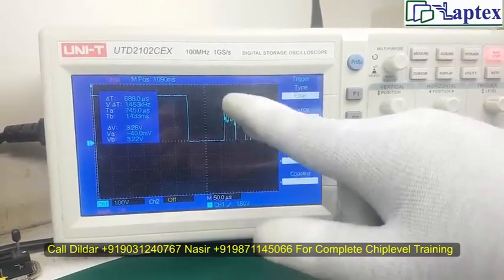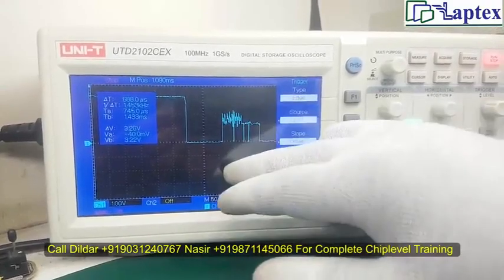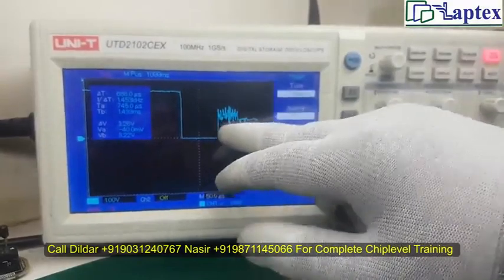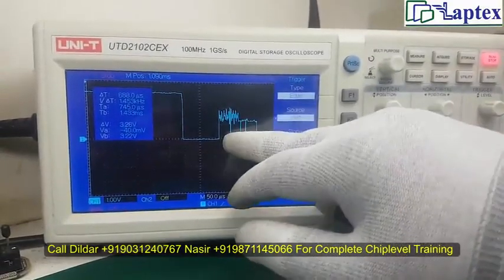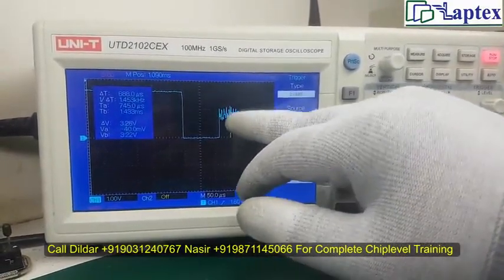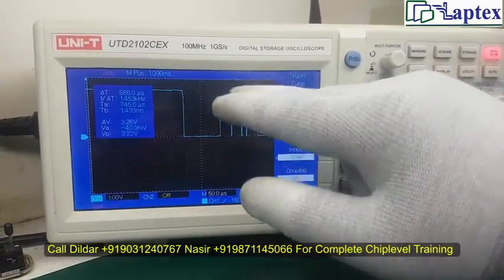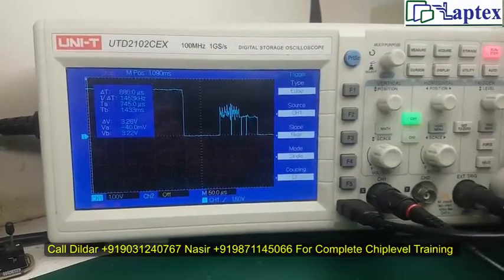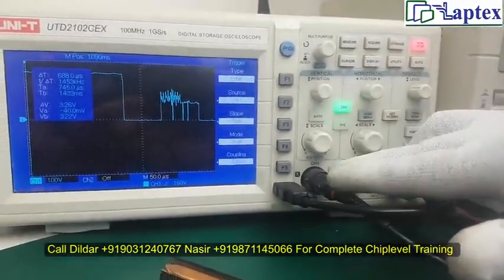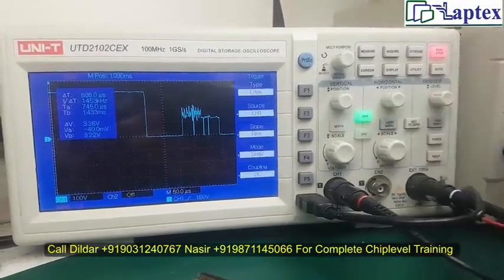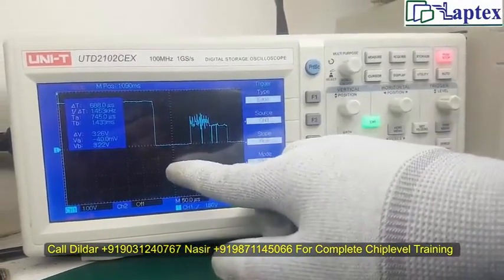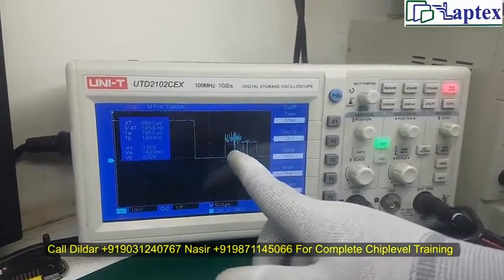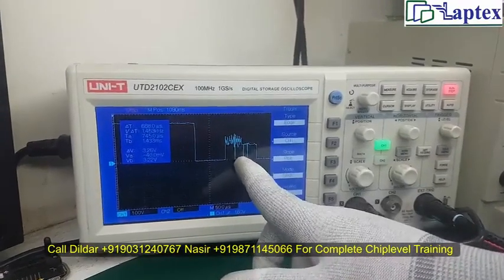The BIOS executes only two things, reading and writing. So this clock gives the time for the reading as well as for the writing. So the timing is the most important thing. While checking the BIOS signal, you may have to use both channels, CH1 and CH2. Why? Because you have to measure it at the rising edge of the clock. So now this is the rising edge and falling edge you are observing on the DSO.